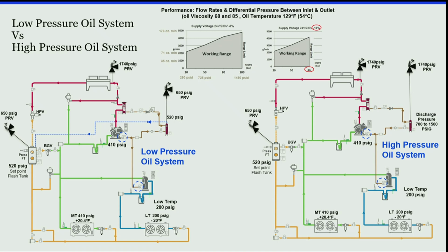So these are all little things that you may not think about, but if you do have a high oil system and you're on the low temp, why is that thing not even opening? You might want to check the voltage on the coil. Little things like that.